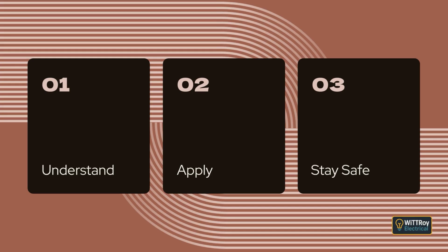Clause 2.3.2 Common requirements. Clause 2.3.2.1 General. Every circuit must be able to be isolated from the supply. Isolation must require a deliberate action so it cannot happen by accident. We use things like padlocks, warning tags, or locked enclosures to prevent accidental operation.